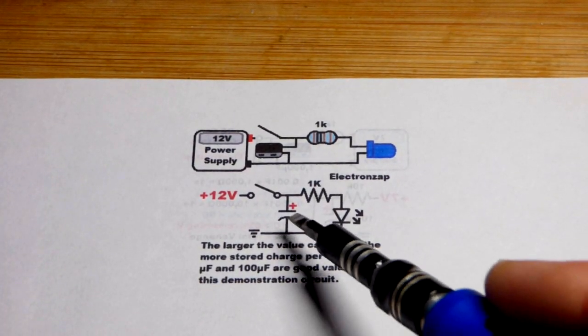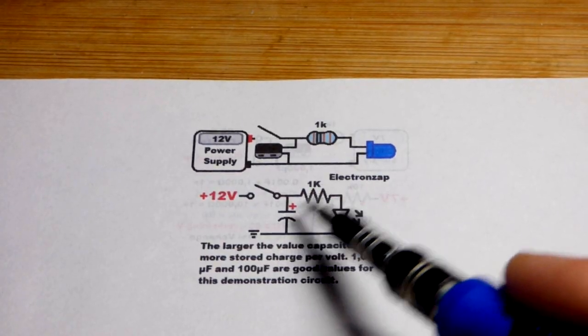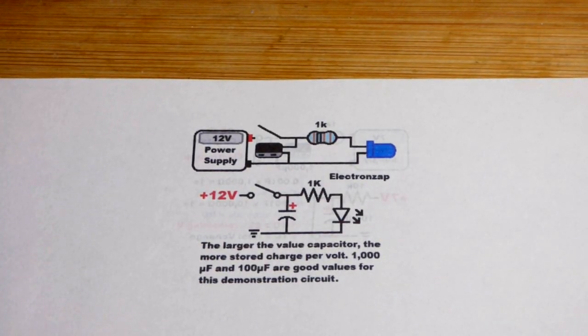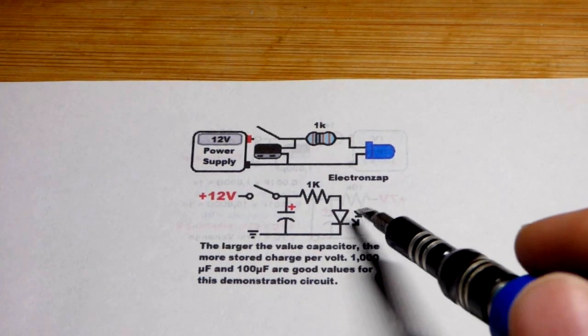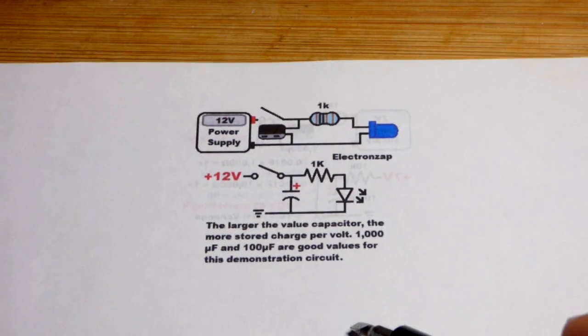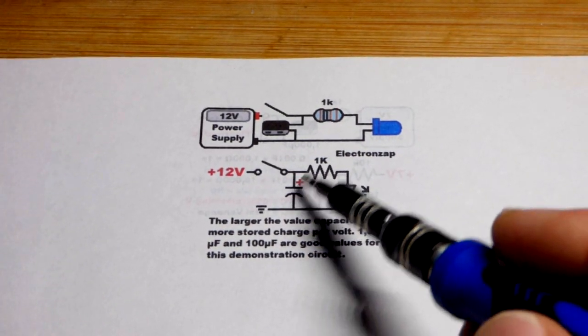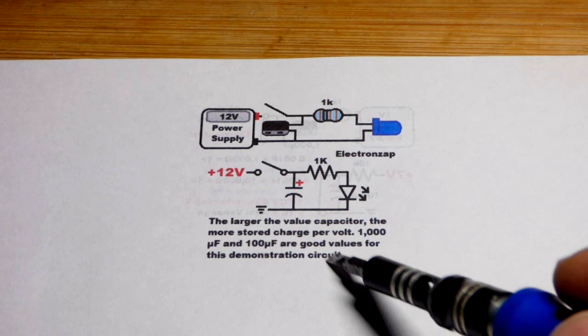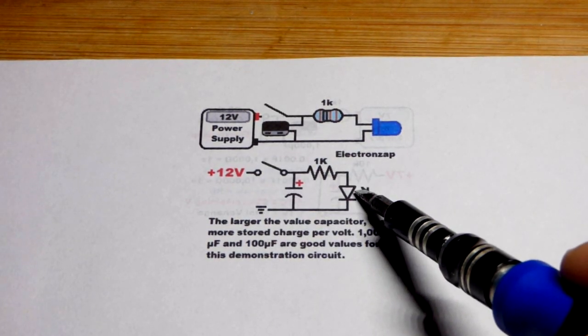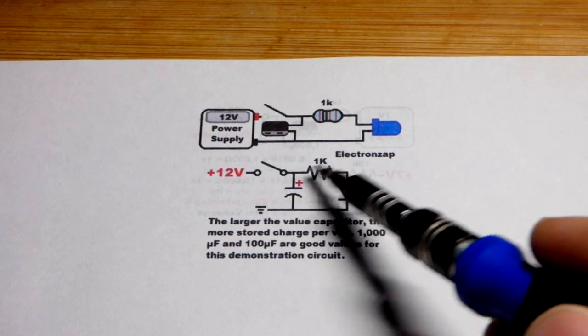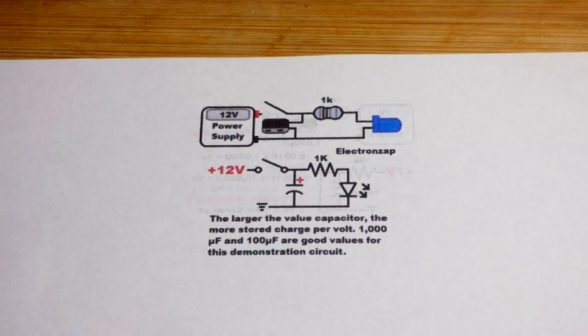And so if you need longer periods of time, you could use this RC circuitry to put a little bit of current through a transistor, which will be on, and the LED will be on for a longer period of time. All kinds of ways to improve this. But yeah, this is a basic demonstration circuit that I do. When I close the switch, the capacitor instantly charges, and the LED is lit. When I open it, then the LED fades off pretty quickly.